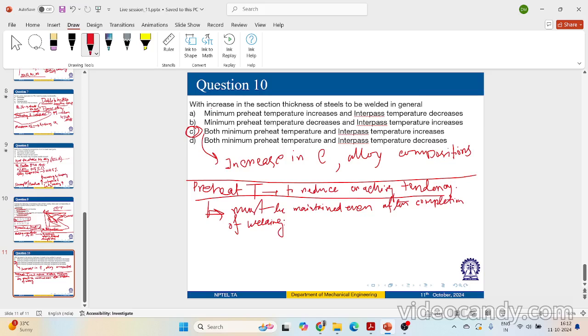Now in applications where your weld metal will be required to respond to the same post weld heat treatment as the base metal, in order to match the base metal strength, you will use a filler metal similar to the base metal in composition.